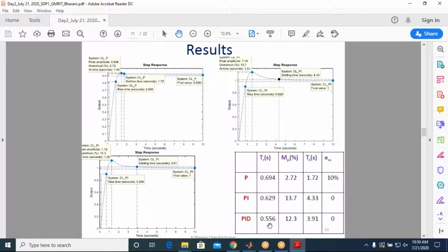So the problem here is, even if the voltage is directly proportional to the speed, due to the inherent nature of the DC motor it cannot go beyond its rated values. Let us assume the rated speed of a particular DC motor is 1500 and it is designed for, say, 20% more, so 1800. If you keep increasing the voltage, it will not go beyond a particular speed because of the inherent capability of the plant.